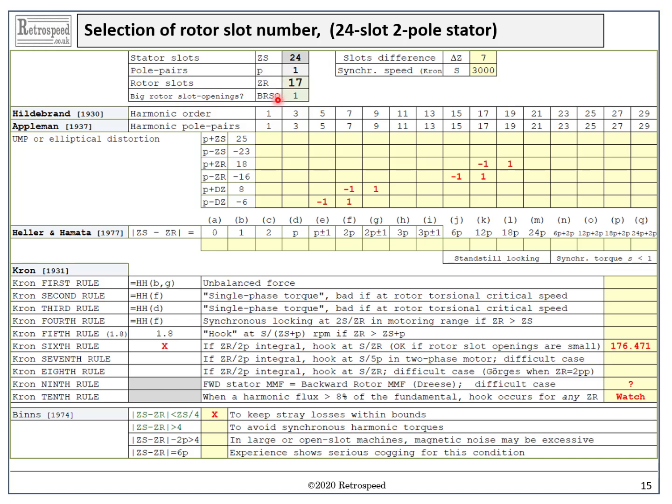Now, the place to start is this large table at the top. And I'm afraid we have to contend with another theoretical complication at this point. If the winding is balanced and contains only odd-order MMF harmonics, we are never going to find two waves differing in pole number by 2. For example, the 23rd and 25th differ in pole number by 4, because they differ in pole pair number by 2.